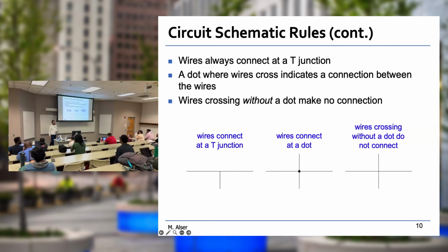Yes, please. Just to clarify, we're not supposed to connect wires like that from the output, right? Excellent, excellent. Don't ever connect two outputs together. We already explained this in the past. So this is extremely wrong, because if the two outputs have different values, the wire will have to pick which value. We have 1 from here and 0 from here. We cannot connect those together.